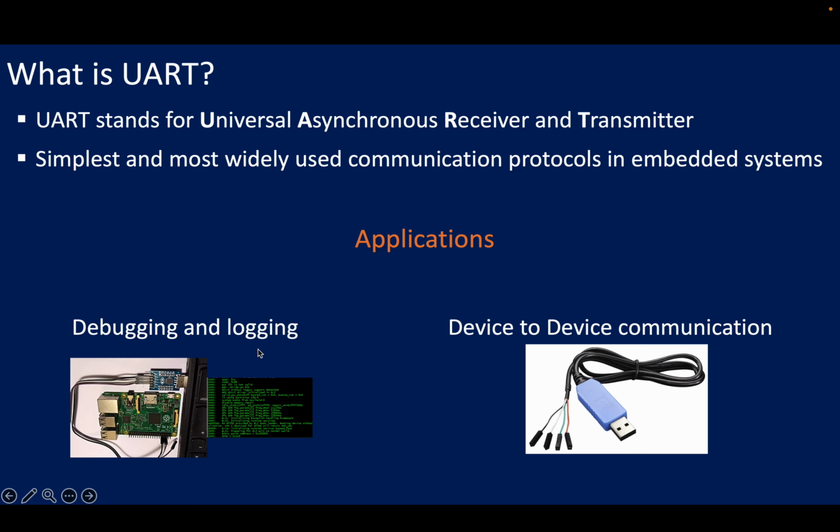Debugging and logging. One of the most common uses of UART is during development. Developers send debug messages from the microcontroller to a PC terminal using UART. It is simple and very effective for printf style debugging.